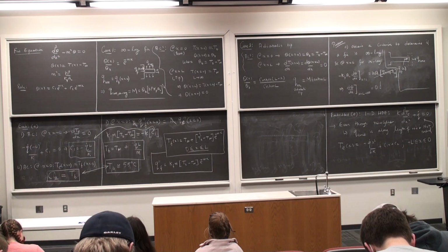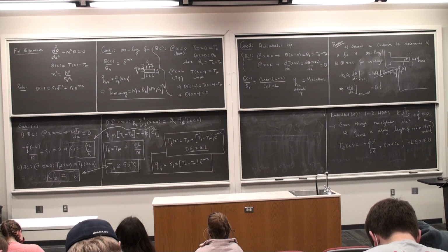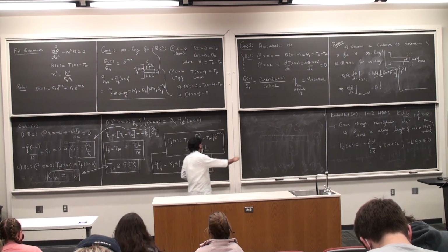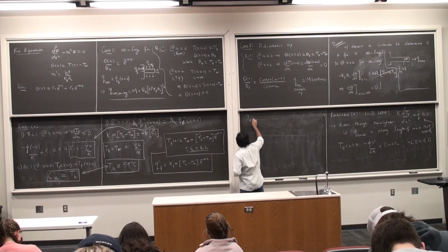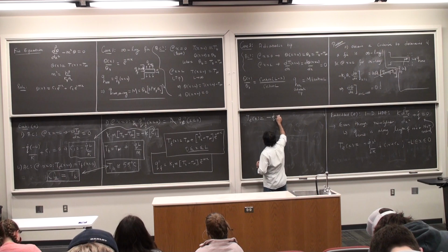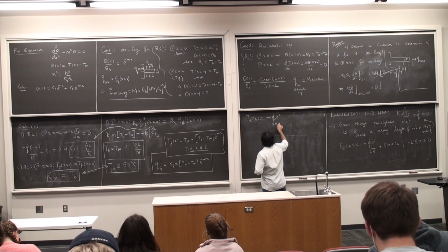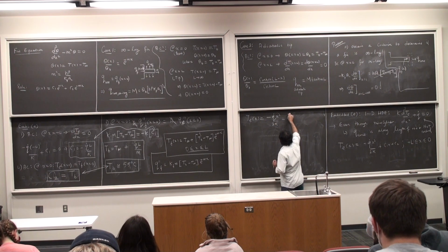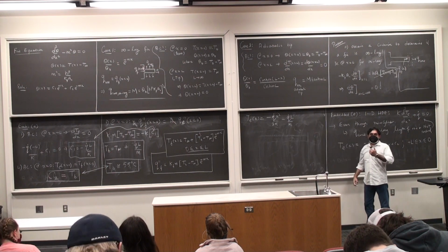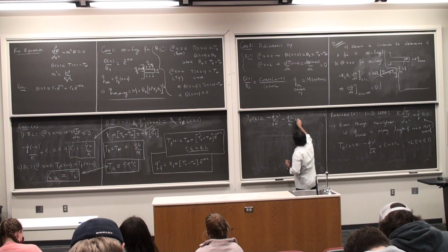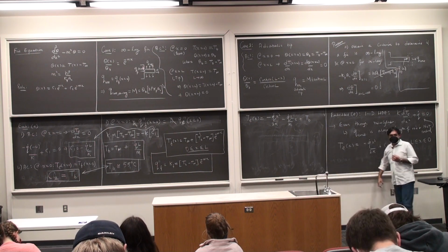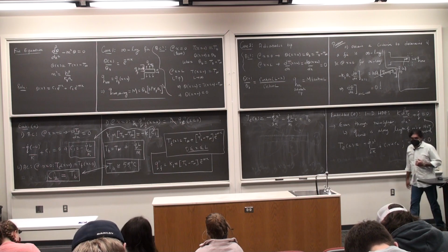Alright, so in summary, this is what we have. The problem is done, but I just have to plot the flux and the temperature profiles. So I have Te is minus Q dot x squared by 2k, plus C1, which was minus Q dot L by k, multiplied by the factor x, plus C2 which was Tb. Then I have Tf as well.